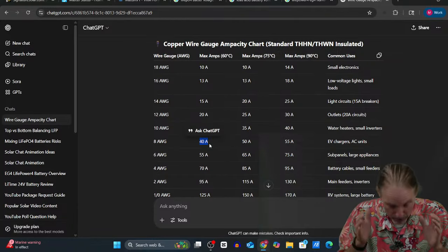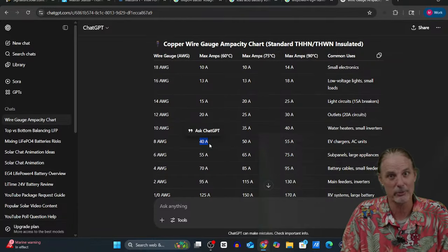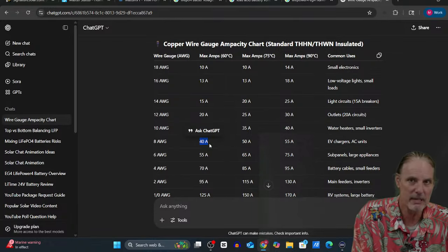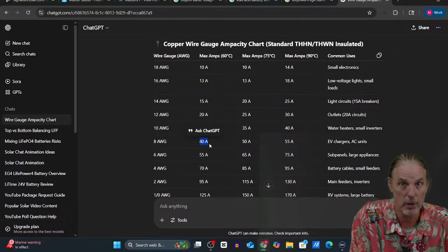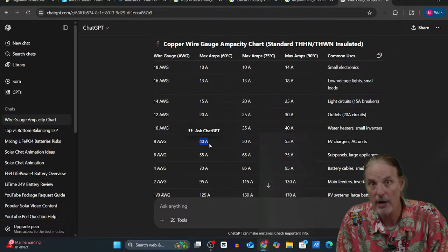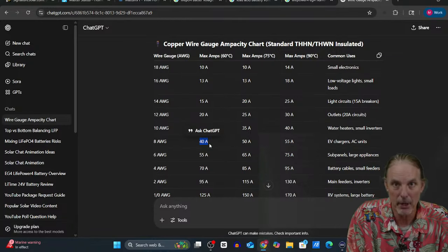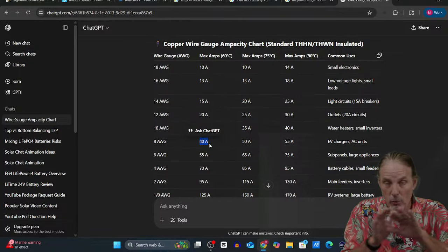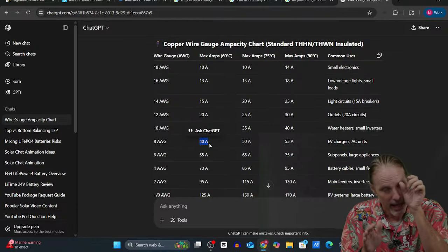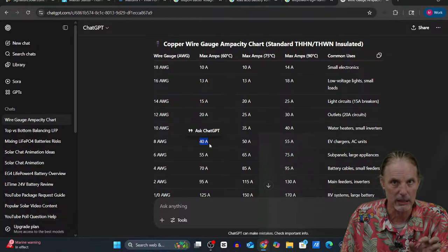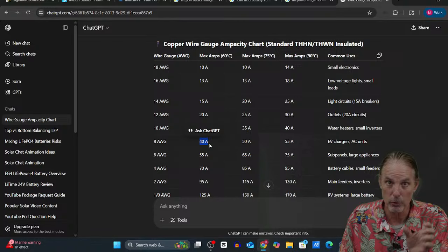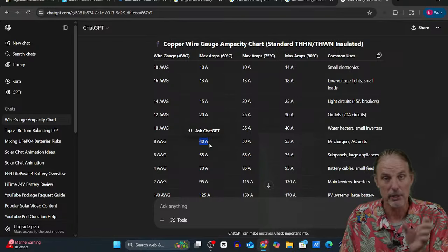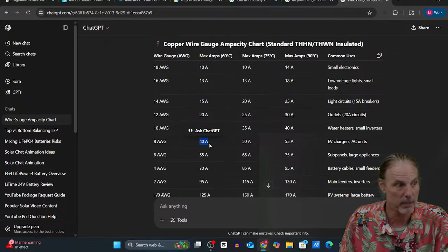And this is where one of the most common mistakes is, people don't take into account: yes, the BMS can support 100 amps or 200 amps, but can the wire of the system, can the bus bars of the system? You want to go through all of your equipment and make sure that the weakest link is what you're putting that fuse on, because that's where you're going to run into the biggest problem.